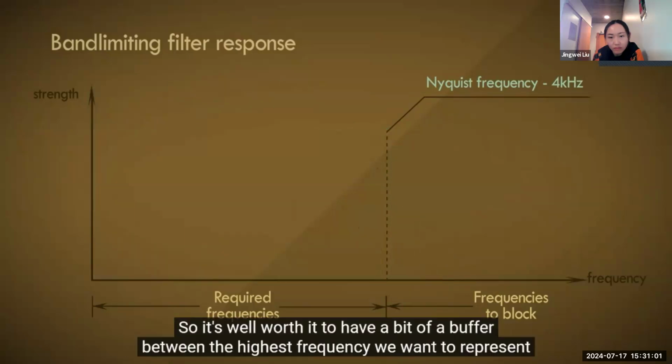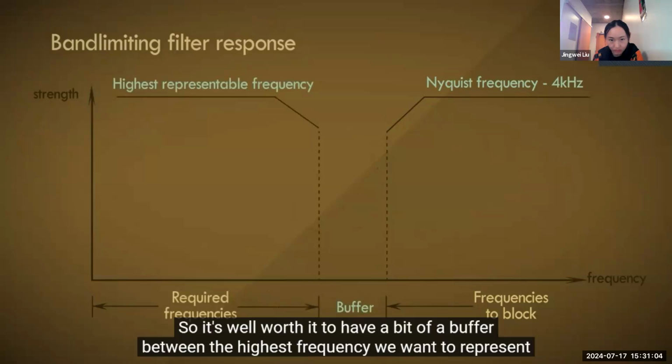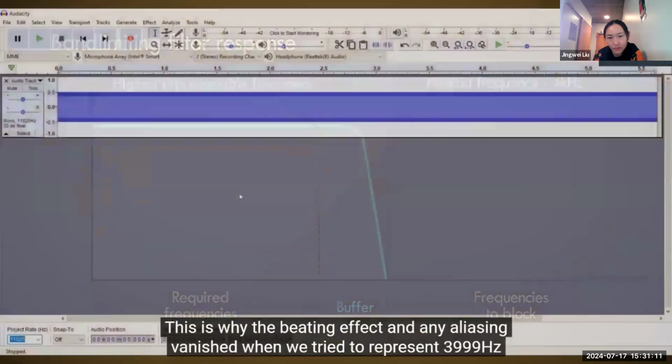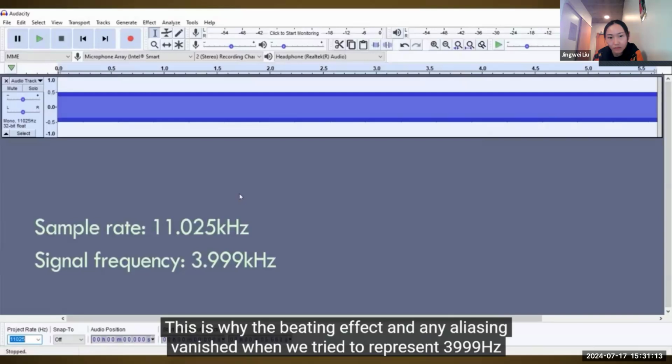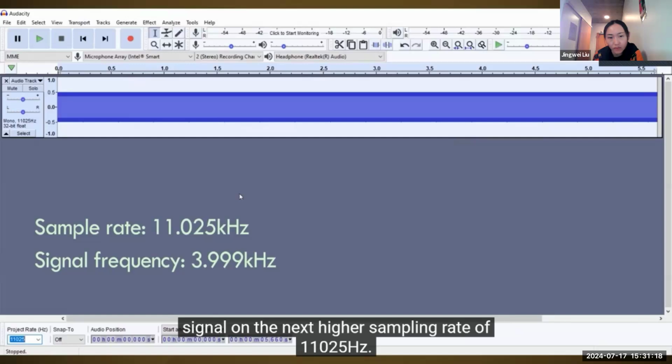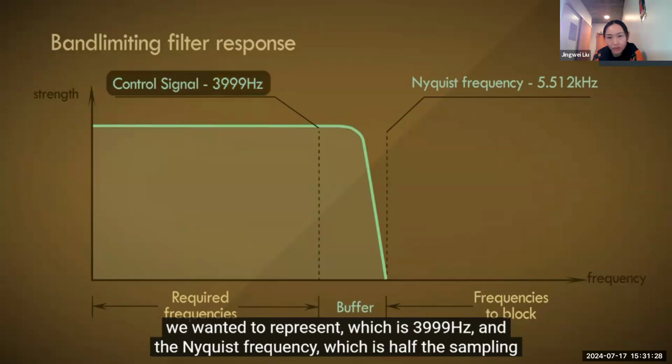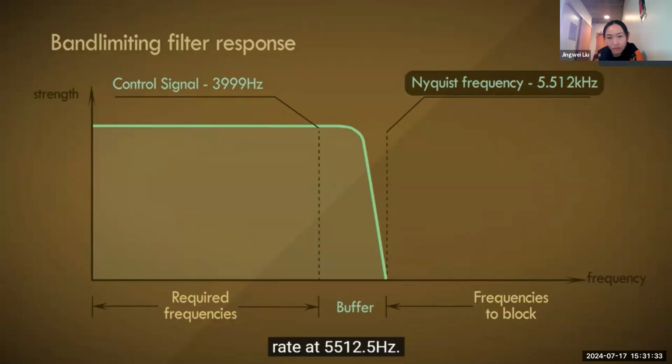So it's well worth it to have a bit of a buffer between the highest frequency we want to represent and the Nyquist frequency above which no frequencies should exist. This is why the beating effect and any aliasing vanished when we tried to represent the 3999 Hz signal on the next higher sampling rate of 11,025 Hz. This meant that there was a considerable buffer between the highest frequency content that we wanted to represent, which is 3999 Hz, and the Nyquist frequency, which is half the sampling rate at 5512.5 Hz.